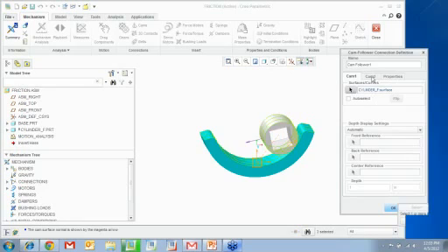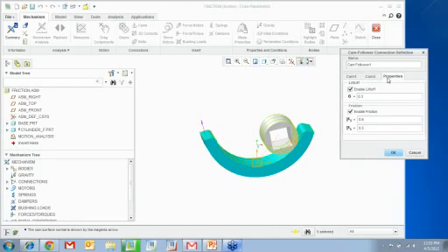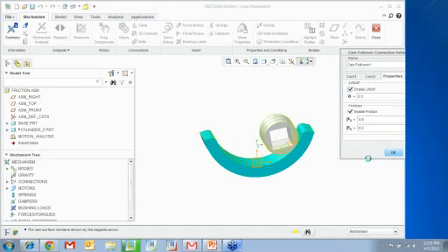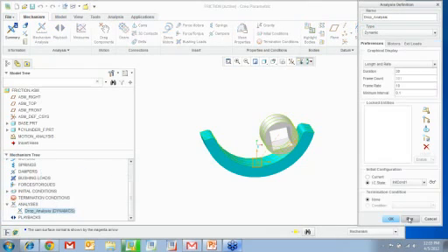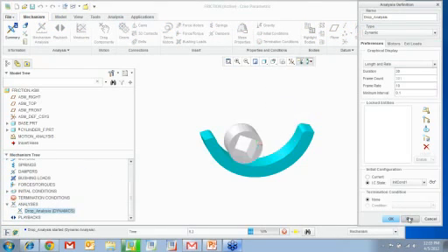There's a cylinder surface, and then there's the base surface, and here I'm saying enable the lift off, and that is the static friction and kinematic friction values. Now I'm going to run a dynamic analysis and say run, so you can see how it slips, right?